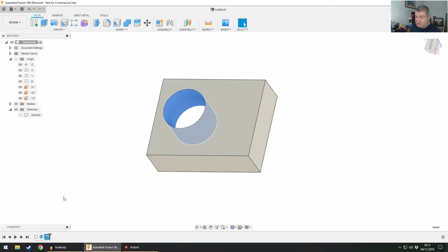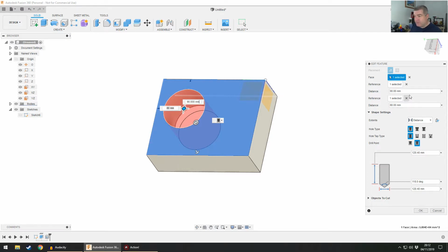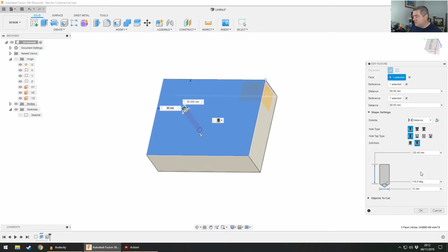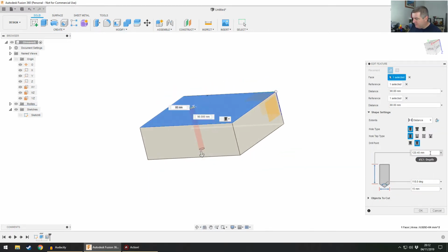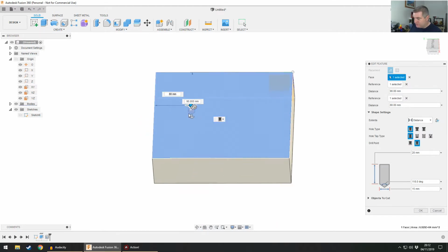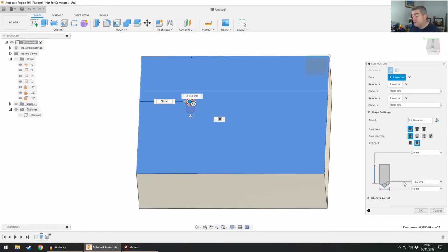And what you can do is select a whole bunch of parameters over here. So there's our references, 90 and 80. Our hole diameter is here at 124, so I'm going to make that 15. Tiny little. Pressing return closes that for reasons that can't be fathomed. Thanks Autodesk, I appreciate it. And if you just want the depth to be like 20, yeah, pressing return does close that function. That's not very good. And then, of course, we can say we want 118 degrees. For all those who don't know, the tip of a drill is 118 degrees. And, of course, we can have flat bottom or pointy.